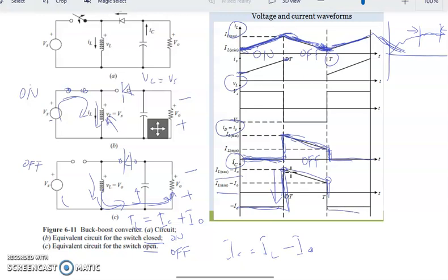And what happens at the output actually? From the output point of view, in terms of voltage Vout and also in terms of IOut, the output is a stable DC. But for the buck boost, the output we plot should be on the negative side. So it starts from 0 and stabilizes like that. So we can see that the output is on the negative side.